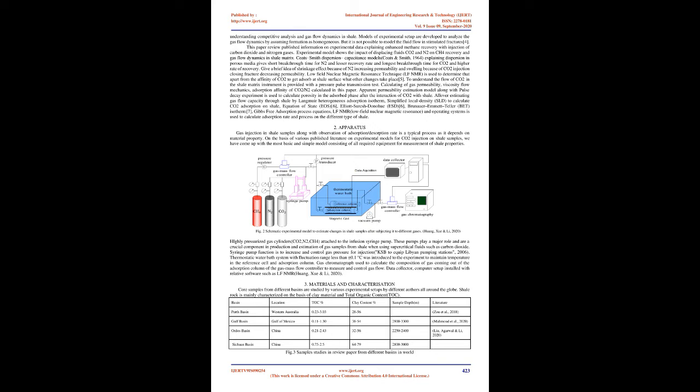In recent years, CO2 injection in shale formations has been investigated with the aim to enhance shale gas recovery, ESGR, and permanently store CO2 gas in the shale matrix, which accounts for 95 to 99% of the total gas fraction injected. Injecting mixtures of CO2 and N2 may potentially optimize recovery of natural gas and sequester CO2 in shale. Several studies specify that CO2 adsorption rate on shale is 5 times higher than that of CH4. The ESGR method is embryonic, as pre-adsorbed methane gas gets released by the influence of CO2 because of the resulting in situ swapping mechanism at the sorption site.